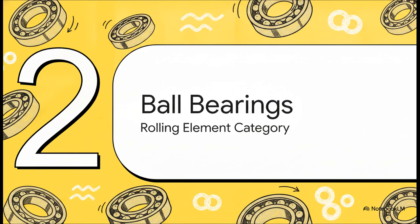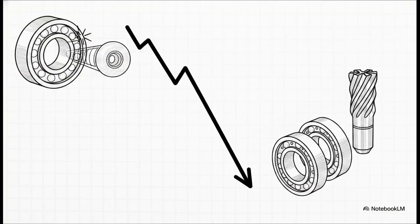Moving on to Section 2, the ball bearing family. So this family uses point contact to reduce friction at incredibly high speeds. The most common one you'll see is the deep groove ball bearing. They're literally in everything, from electric motors to skateboard wheels. They are fantastic for high speed and radial loads, but man, they handle misalignment terribly. And watch out, because uncontrolled axial float here causes fretting and highly unpredictable behavior. Just look at the bearing life equation, specifically that exponent of 3. That means bearing life drops off a cliff as the load increases.